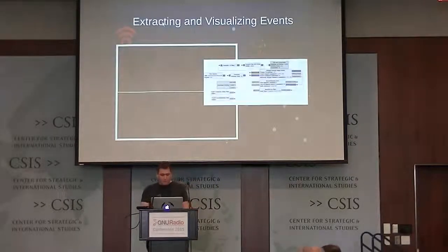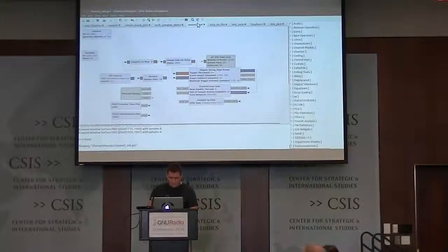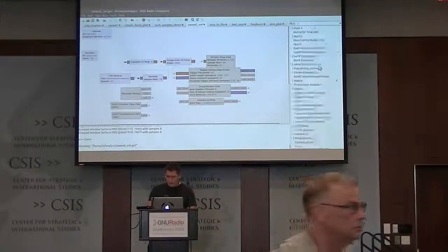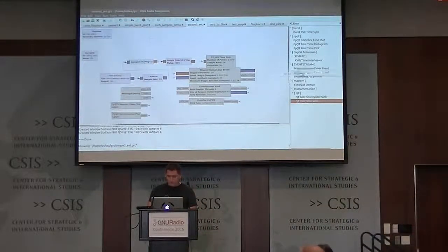So we can use that same kind of message-based plotting back in the Z-Wave streaming example. We saw how we could trigger on the I and Q values rising over a certain value. So what we're going to do is extract a message every time that happens. If we put a time sink, actually there's already one there. We're going to take that raw I and Q and compute a magnitude squared value, and then run it through a single tap IIR filter and do some smoothing on it.